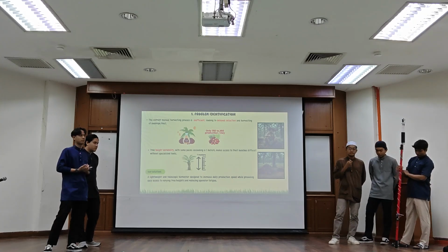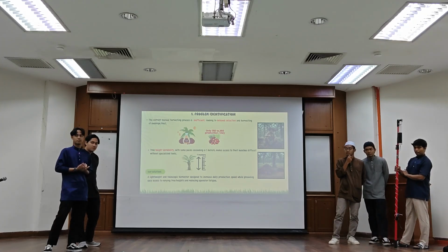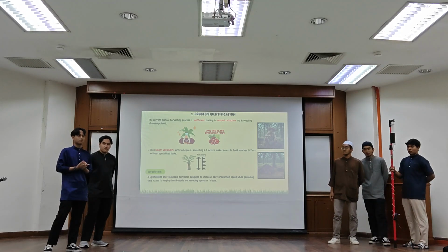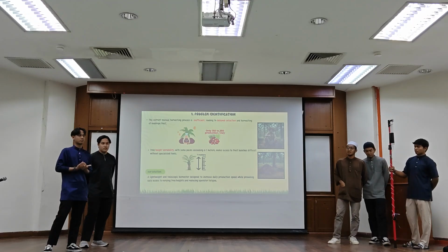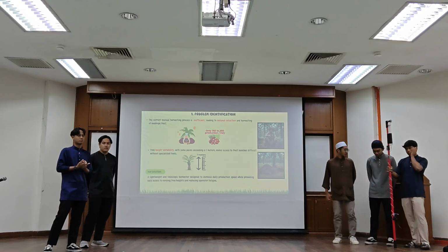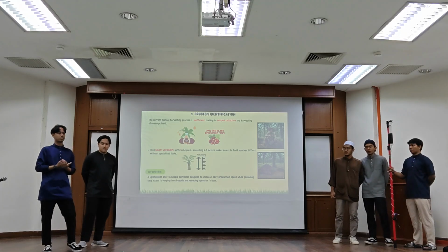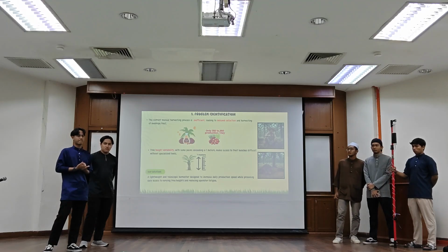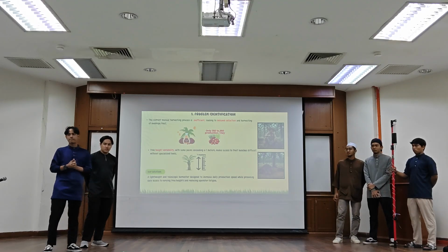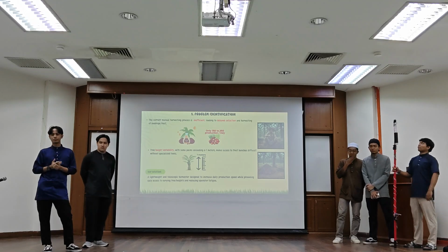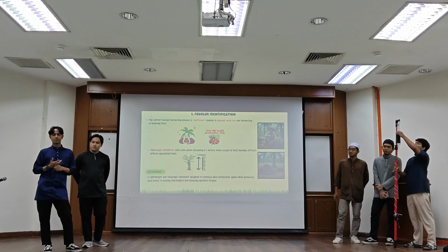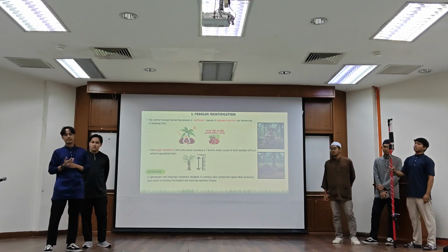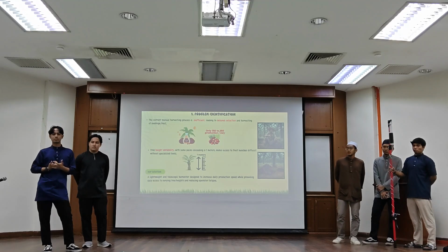Okay, your design validation, this one you can keep, but you have to justify that the 5 kg is related to that, because that's what you put as your engineering target. Is there a standard, like OSHA or some health standard, for a worker to move something from one place to another? If it is below 3 kg, they can work for 8 hours without fatigue. It's like what we do for acoustics: it should be a maximum of 80 decibels for 8 hours, otherwise you will lose your hearing and safety. That's a standard for everything. So if there is a standard and it says 5 kg, then that's your justification.